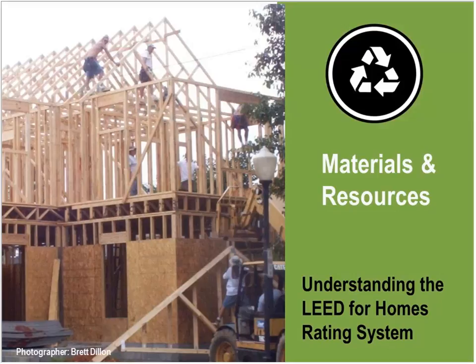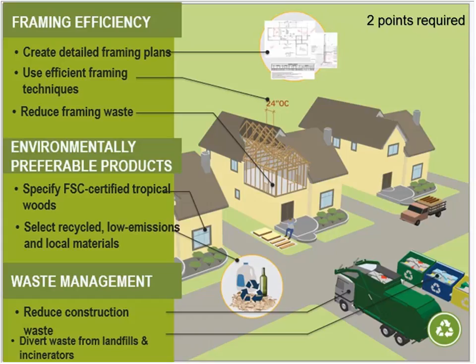So materials and resources is our next category, or the MR section. 2 points are required in this section. Really what we're looking at in this section is detailed framing efficiencies, framing plans, which a lot of that's getting removed in V4. Doing advanced framing like 24-inch on center, so getting more stud space, doing less wood, and being able to get more insulation in between the stud space is also a benefit to your energy and your HERS rating.